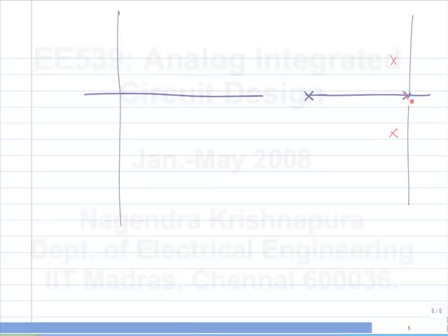So maybe you will have 3 poles. You have something like this and these 2. Perhaps the loop gain would have done this, because of the complex poles it will give you some peaking. So what will happen in the phase domain? It would start from minus 90 and with 2 complex poles, you can go to minus 270, right?